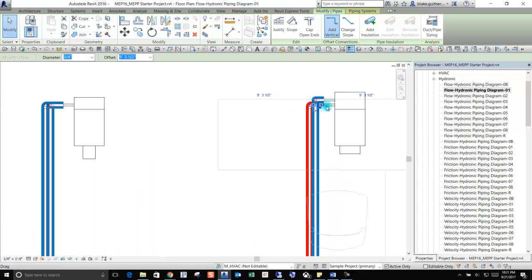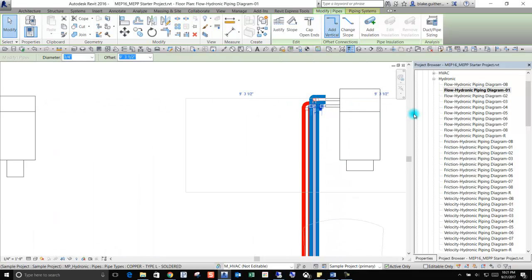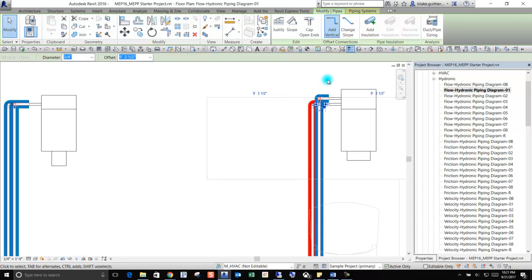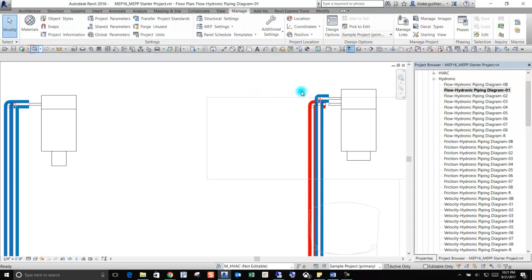We're like, oh, okay, we got to connect that to the VAV box. You could also see that with a disconnect. But even if you have everything connected, if your VAV box has 0 GPM, this method would still indicate an error before you size your pipe.